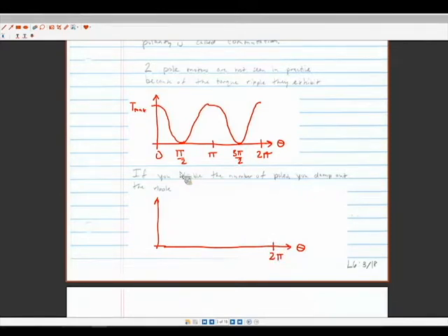So you have some sort of Tmax you get out of the system, and then the actual torque profile is a ripple, as you switch between the different loops of the rotor. The reason I mentioned this ripple is quite important. For the purposes of modeling motors in this class, we're not going to really model this commutation. We're going to say this ripple is so small. But if you work in any type of robotics, motion control, etc., this torque ripple actually becomes quite important.